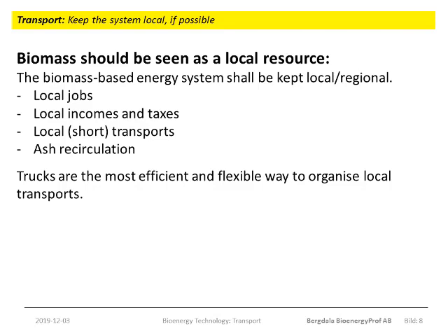Each and every loading and unloading operation, unless the material is handled in closed containers, will produce material losses. Solid biomass will always release dust when poured from one vessel to another. And if each loading and unloading operation generates a material loss of 1%, you will want to keep a low number of such operations in the system. Unless each and every end user in this case has a railway track on site, there will again be one loading and unloading operation at the receiving end.